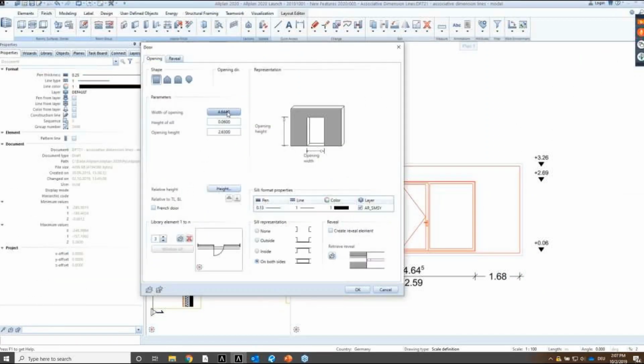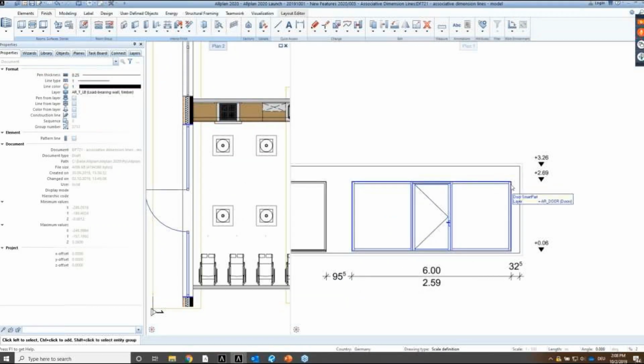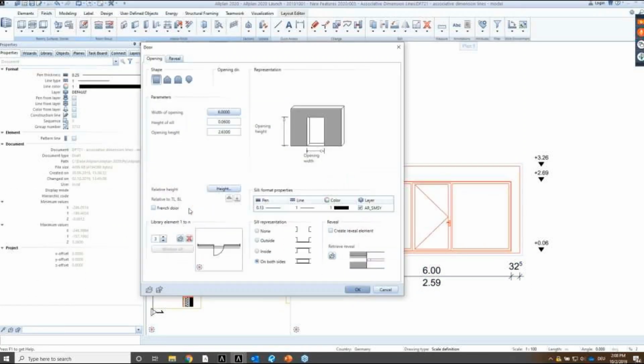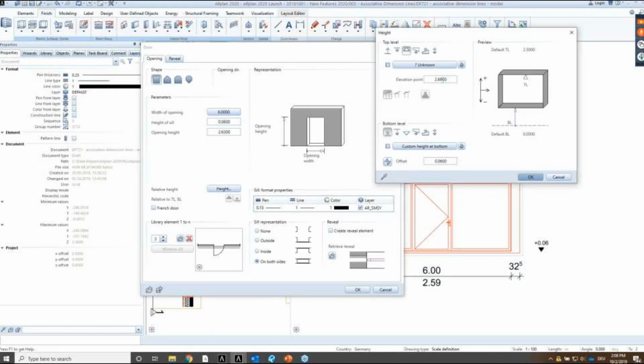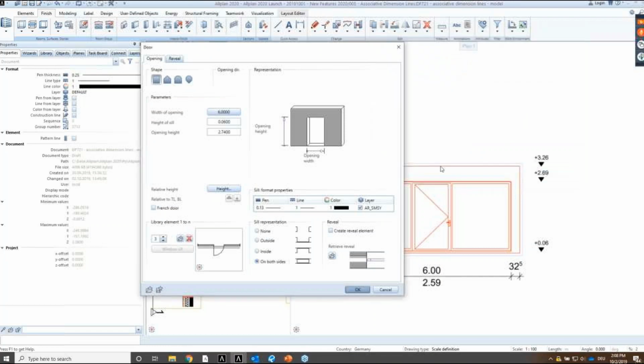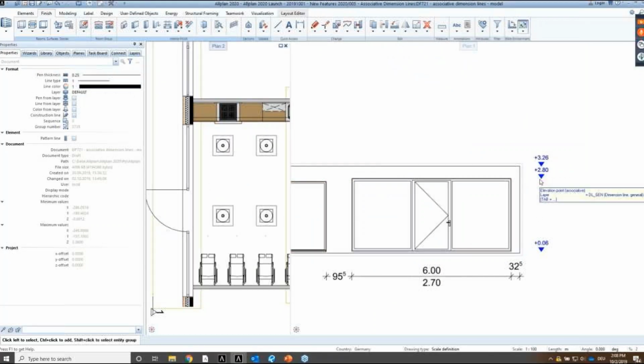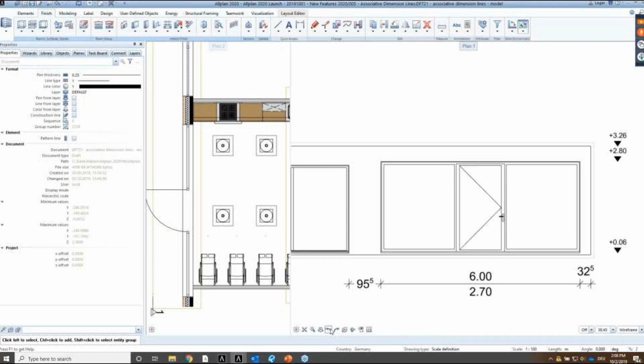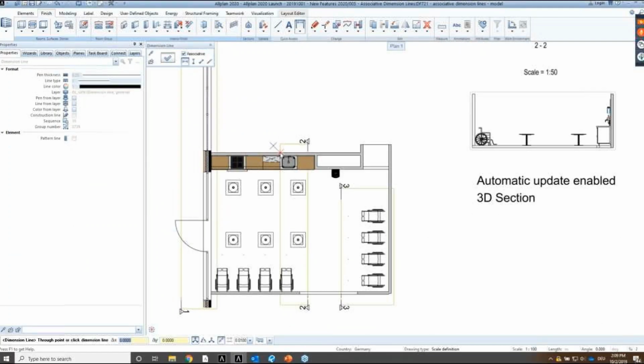And now we make a change anywhere in 3D on a plane, doesn't really matter. So we change the opening, and now the dimension updates by itself. This is something everybody wanted, because imagine for a montage plan, somebody just moves a purlin and you don't know exactly in which sections and which montage plan or even reinforcement plan there was a dimension. So for formwork detailing, this is marvelous.